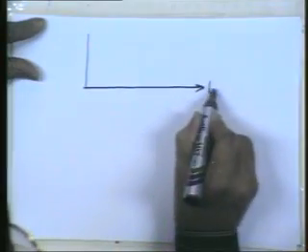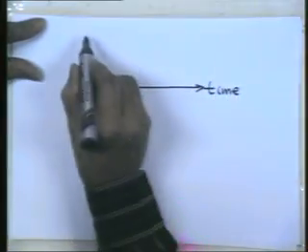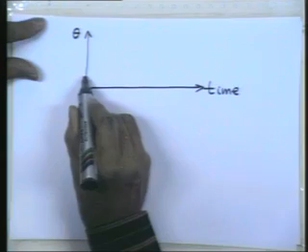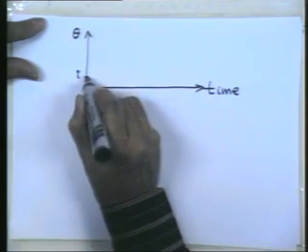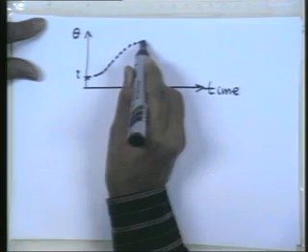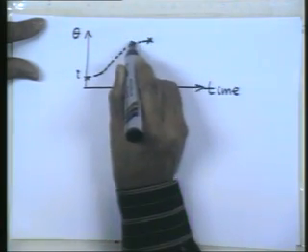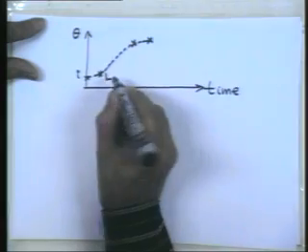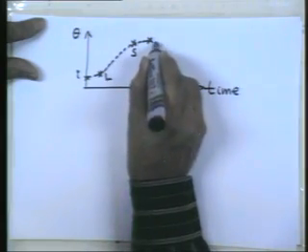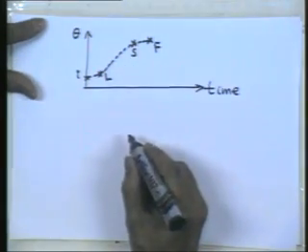Okay. So you look at the motion that you are asking for. So there is an initial position I, there is a final position, there is a set down position, there is a take off or lift off position, and corresponding time durations.